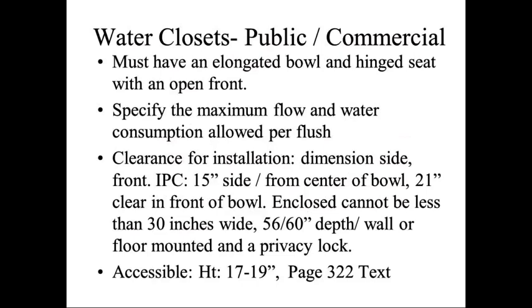In commercial, you have to have an elongated bowl, so you need to make sure you specify that. A hinge seat with an open front. You have to specify the maximum flow and water consumption allowed per flush for that jurisdiction.